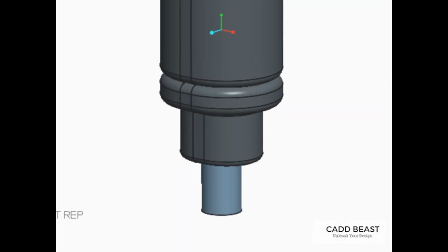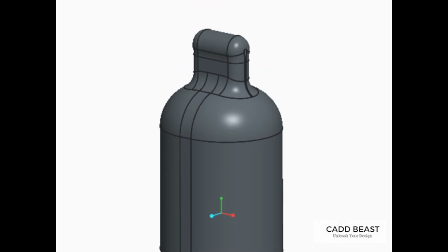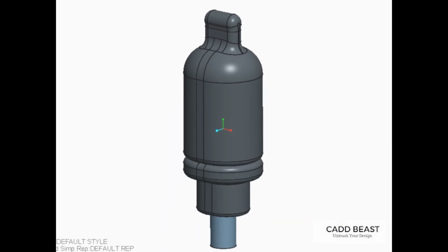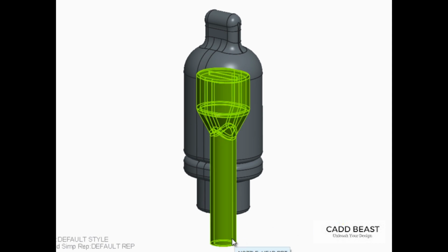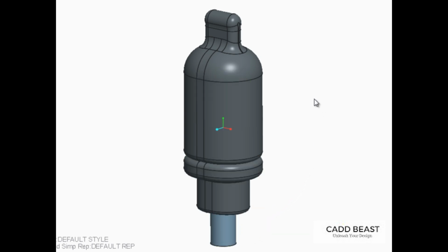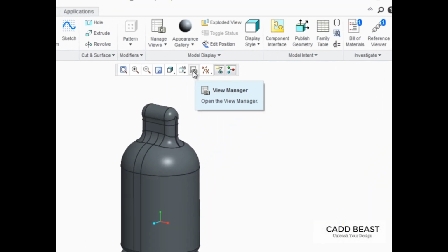In Creo Parametric, you can add flexibility to any component that has already been placed in an assembly. Many designs contain flexible components, such as springs, clips, rubber washers, and so on. In this assembly, we have a plastic water nozzle traveling through a flexible foam housing, and then the flexible upper foam housing fits over both, fitting snugly to the lower housing.